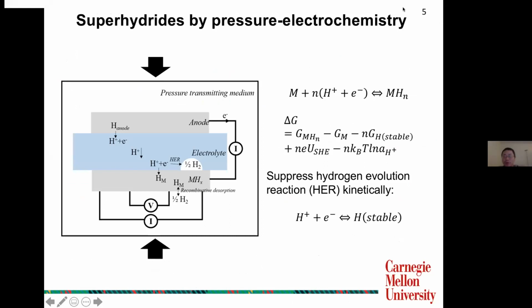I think we want to make the pressure as moderate as possible, but that depends on how we can optimize our other conditions. So this is the result of the multi condition. We can change the temperature, pressure, and also the composition of our system. So maybe for this composition, we need to have very high pressure, but maybe if we change some other composition, the pressure can be made much lower. So this is an optimization of different conditions together.